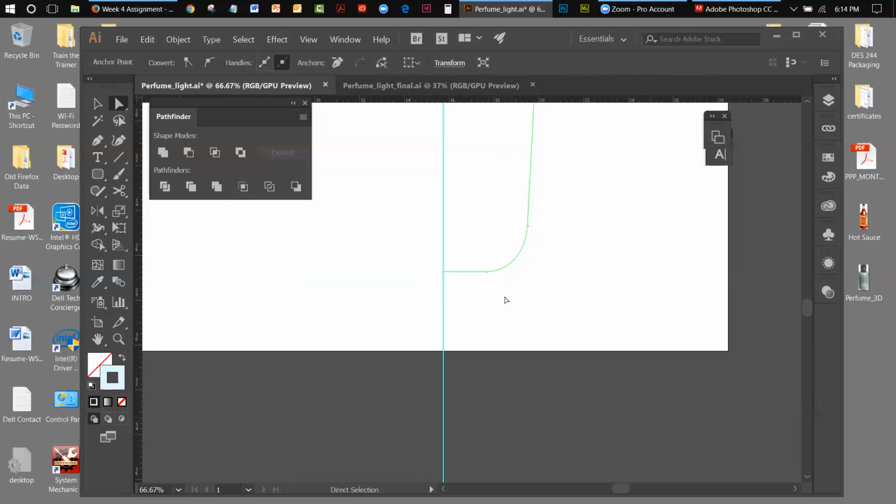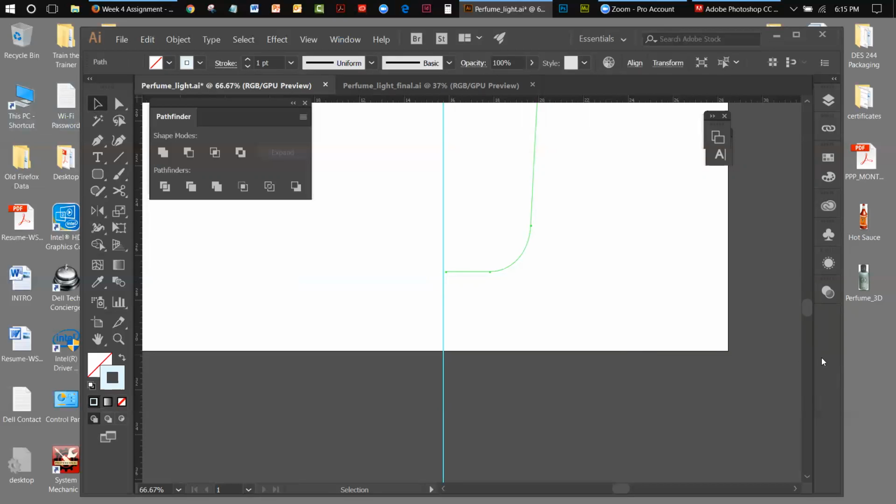I have a question on that. Do you have to hold down the shift key when you're moving it back over? Because when I did that, it moved my whole bottle over. That's because you probably didn't select the individual anchor point. If I click on this and if I click there, the whole thing selects. And if I hold down the shift key, you see what it does? It moves the whole thing over. Control Z to undo it. What you need to do is use this tool right here, not your regular selection tool. Where did it go? Did it come out?